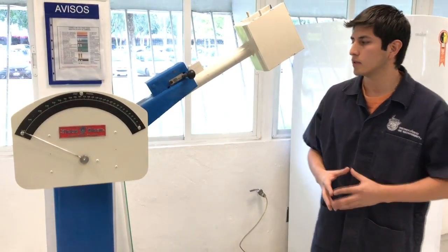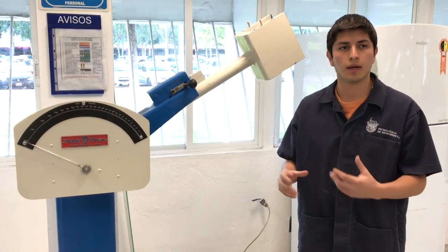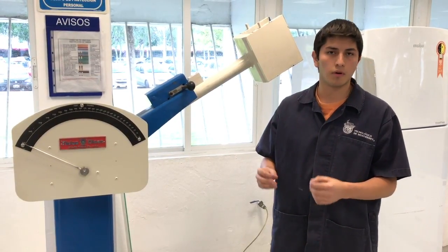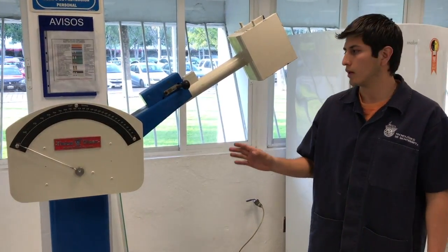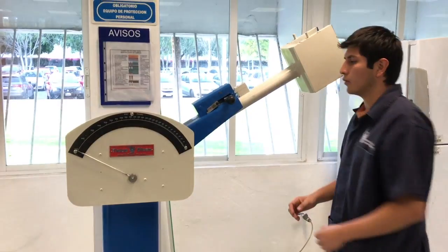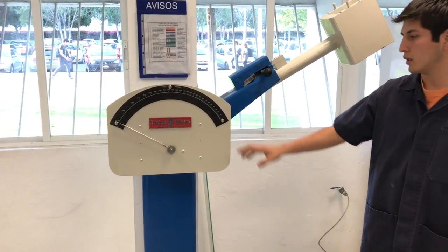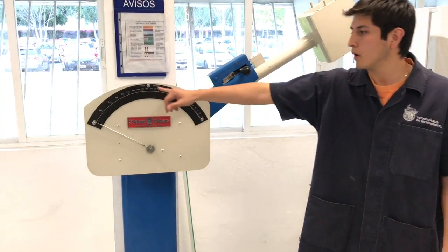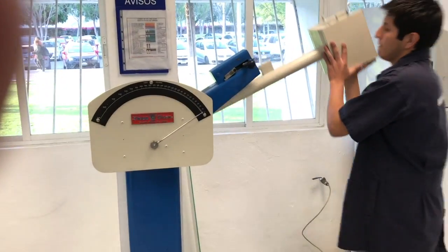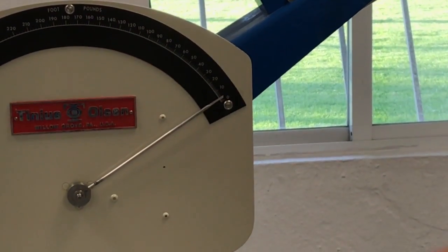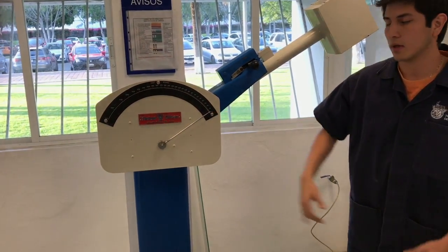For this type of test, it's really important to know that the machine that we're going to use is calibrated, because this is going to prevent some percentage of error that we don't need to have if we calibrate the machine in a prepared way. For example, in this pendulum, we can know if it is calibrated if, without any material, it goes to 0 foot-pounds. For example, here we're going to release the pendulum. Here we know that this time we have not calibrated the machine correctly.